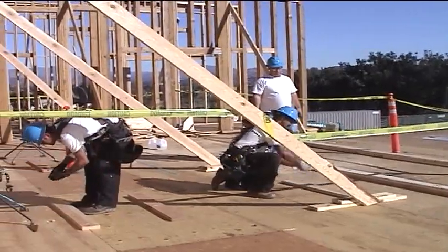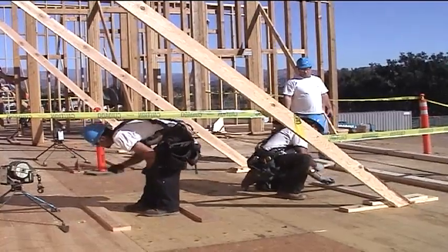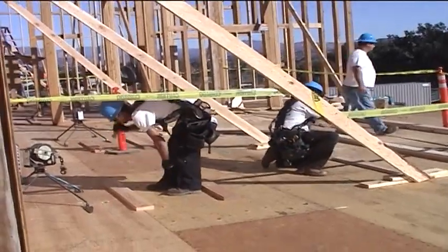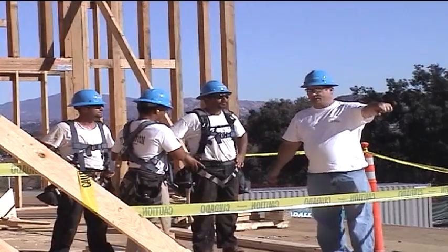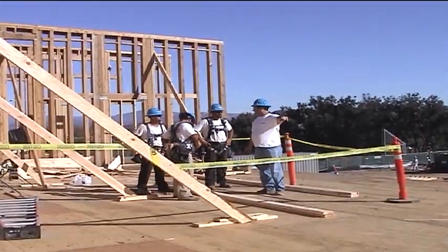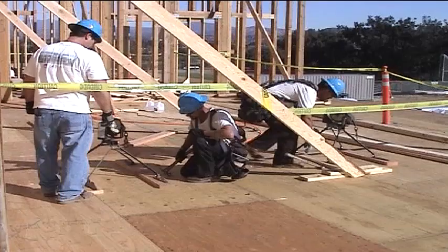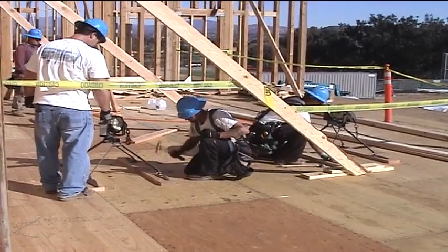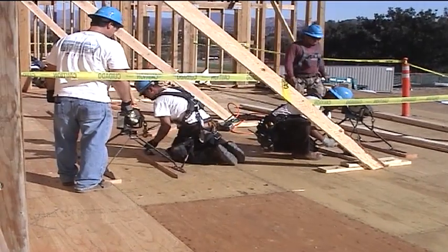The safety monitor must be able to recognize fall hazards and be on the same working level and within sight of employees being monitored. If a hazard appears, or if the employee is acting in an unsafe manner, the monitor must take action by communicating orally with employees. The safety monitor cannot have other responsibilities that would take their attention from monitoring employees.